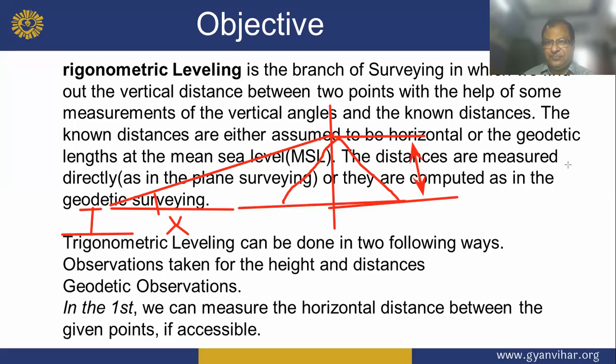Now if you have found this distance, then I think you can find it by tan theta is equal to sin theta upon cos theta, where theta is the bearing. You have found it from the theodolite. And after that, you will find out what this height is. And after getting the height, you will add, what will we add? You will add the mean sea level.